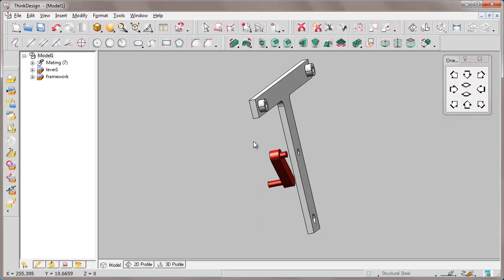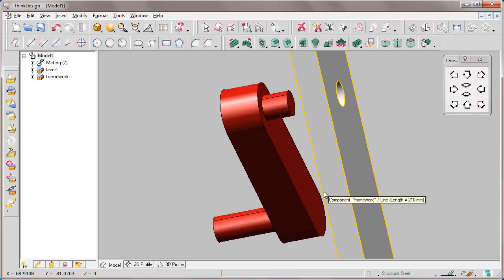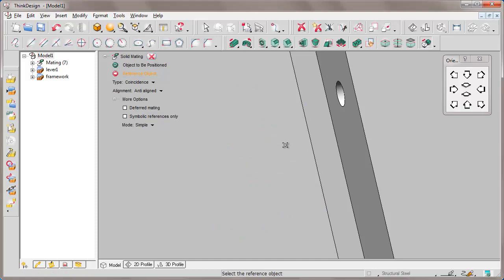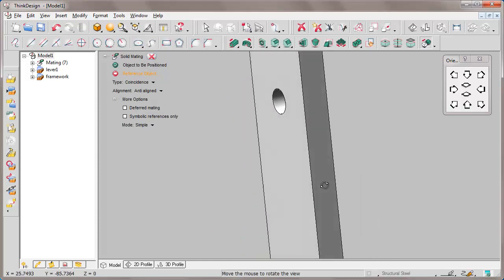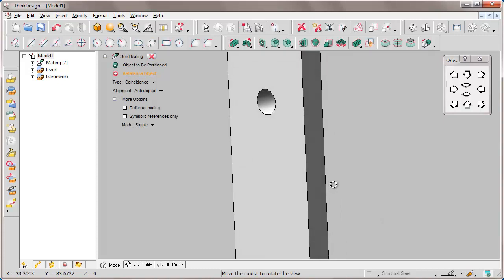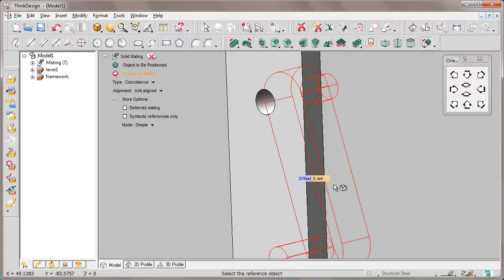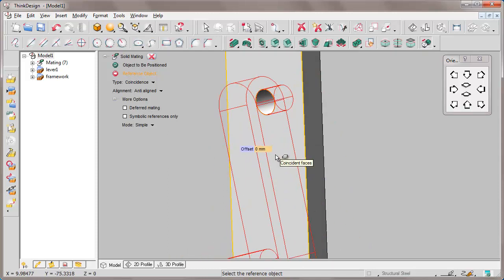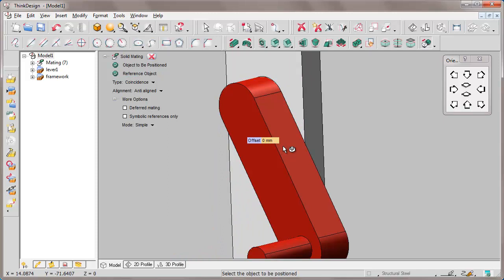Let's now set another constraint, always simple but of coincidence. We position ourselves appropriately. Select the face and state that it must be coincident in abutment. So, anti-align, and in the options we see it's already anti-align with the face of the framework this way.